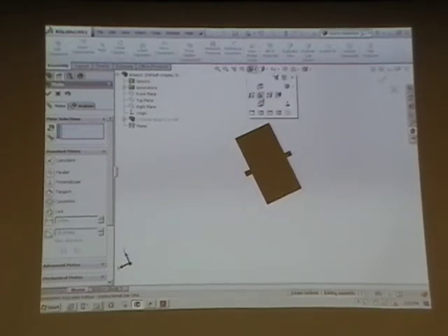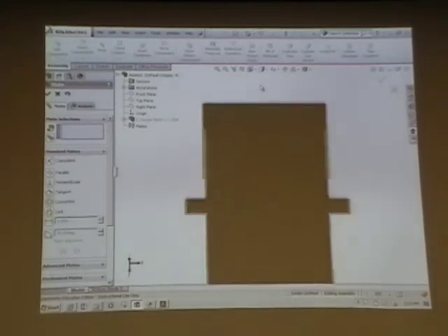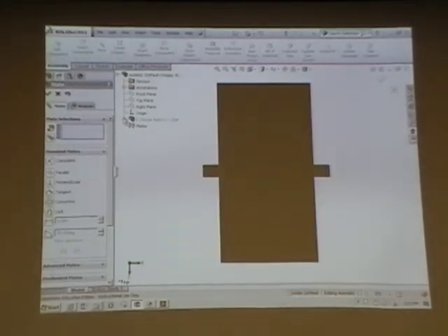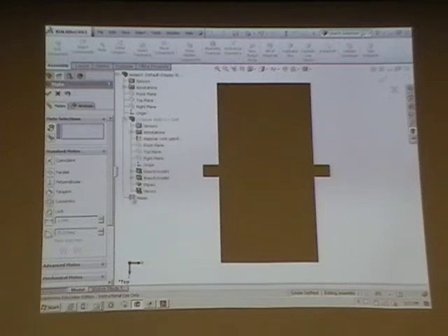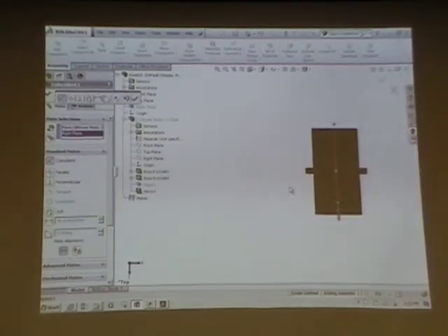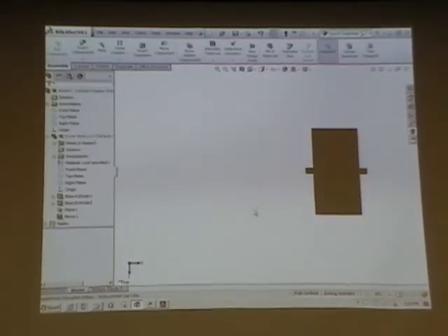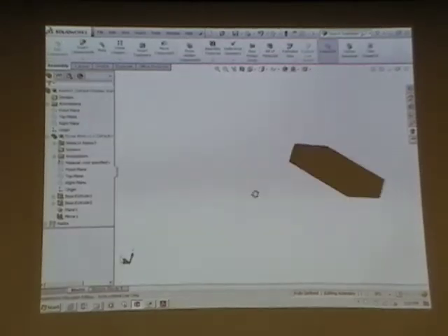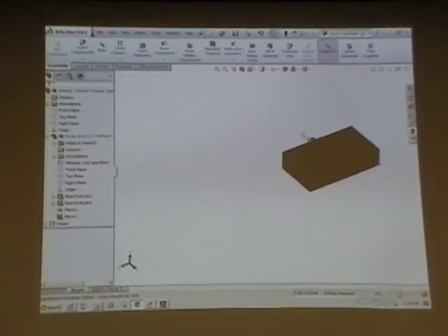In the rover body, so let me expand this, Plane 1 was created for you as a convenience to be the mid-plane of this rover body. So I can take this Plane 1 and mate it to the right datum plane of the assembly, make those coincident. So now my rover body is fixed in a logical location relative to the assembly references.